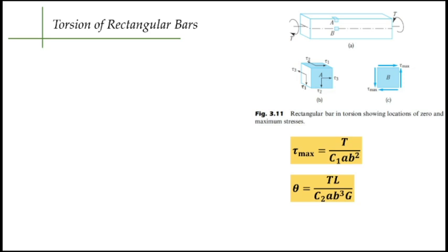Okay? And also one thing to remember as well, that the distribution of your shear stress is not uniform, but rather linearly distributed over the radius. The maximum shear stress for circular shafts happens at the surface. And at the very middle, there is zero shear. Okay, so it is linearly distributed.